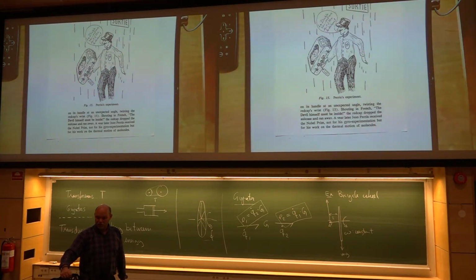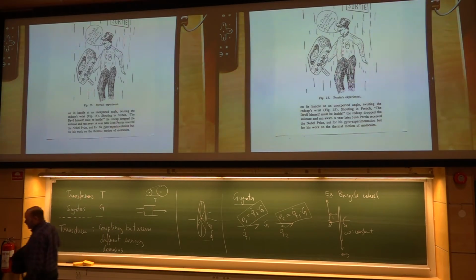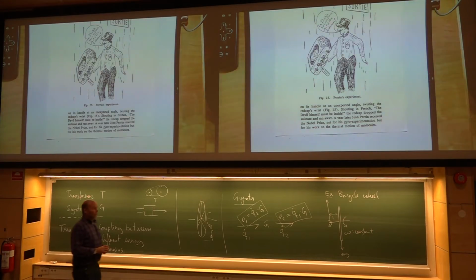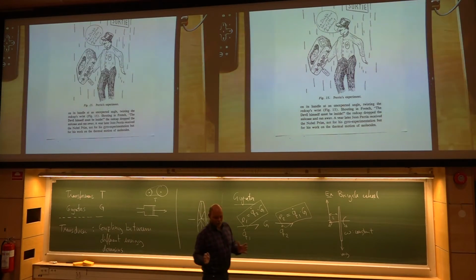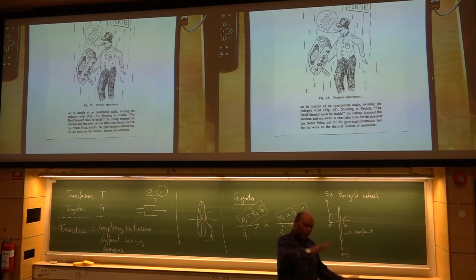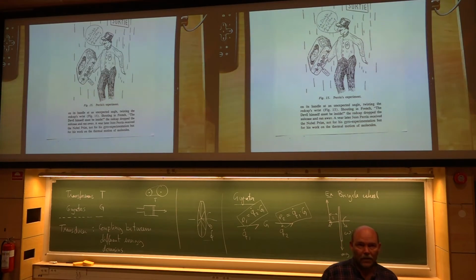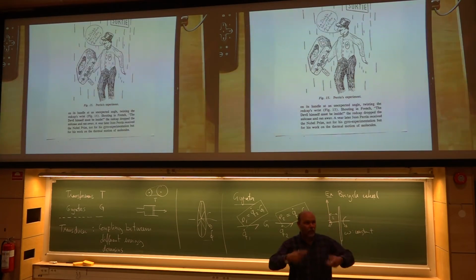What would happen is it would start to slowly rotate in this direction, depending on how fast I can get this wheel to spin. So that is a stabilizer for you. They use it on passenger ships that shouldn't rock too much, so the passengers don't get sick. They have stabilizers like that, a heavy flywheel that rotates. Then the boat doesn't like to really flip over.